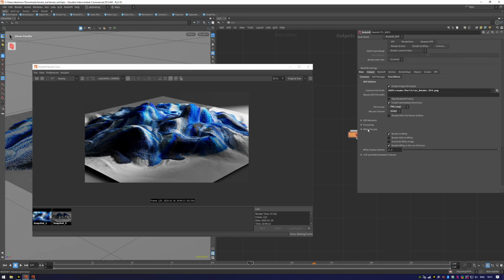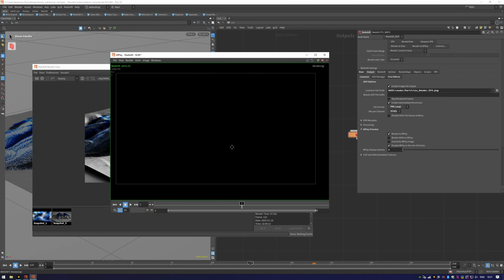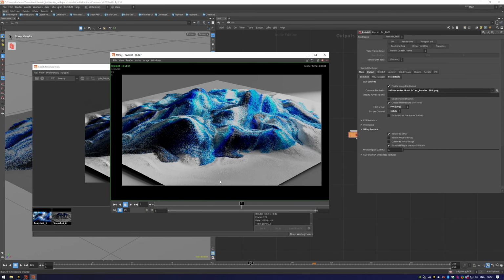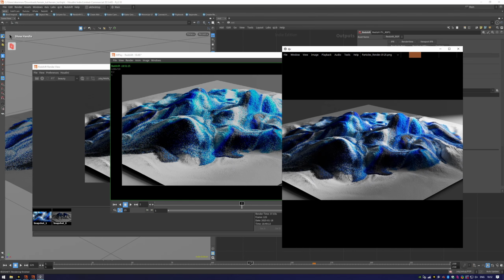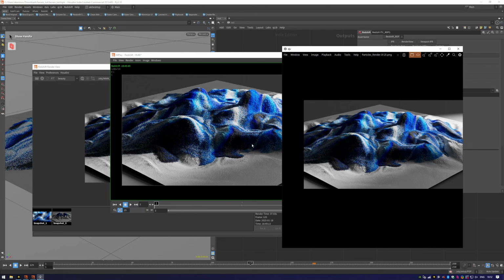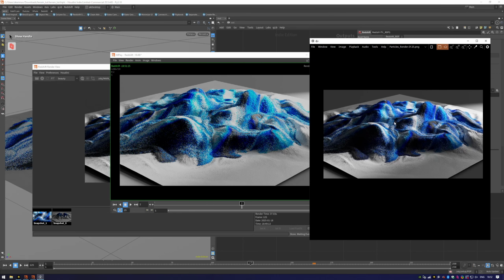Also in the mplay preview, you can put 1 here to display the gamma. Then if you hit the render to disk button, it's not going to look correct in the mplay. Wait a minute. As you can see, after the render, it doesn't look correct. The previous render looks correct, but this one is not. But it's actually correct, because if you take this frame that we just rendered, as you can see, it looks the same. But I'm viewing this frame in this DGV view, and it doesn't really match. It can be just the default Windows viewer as well.